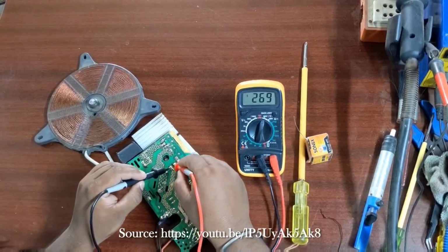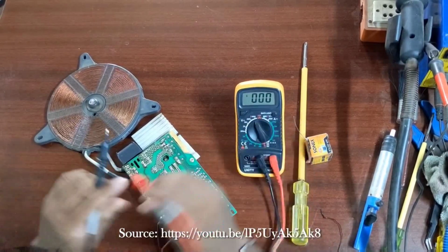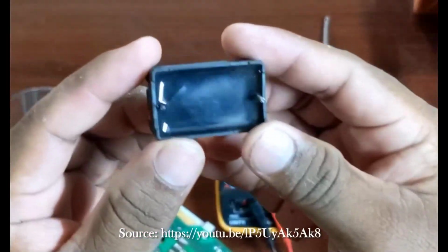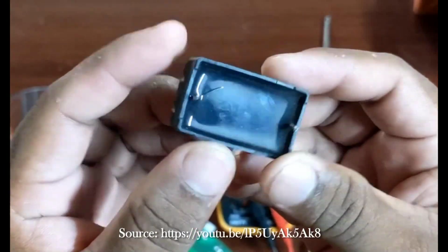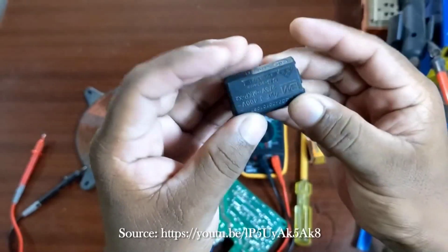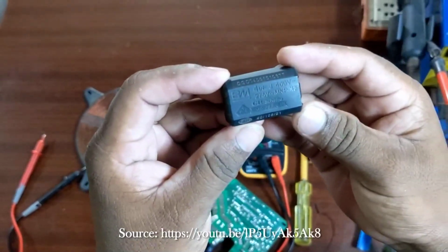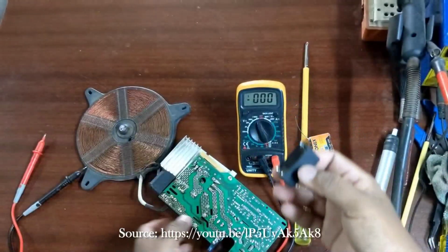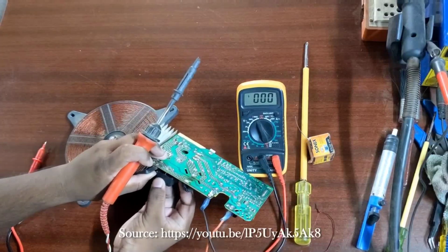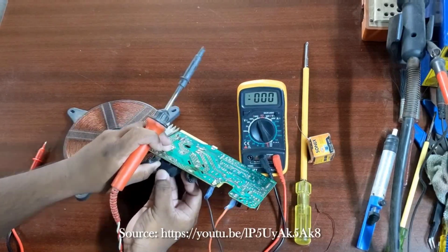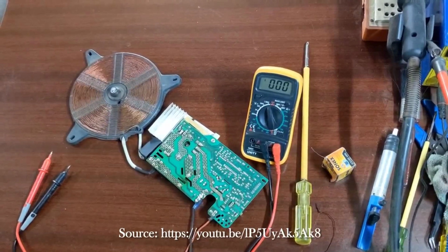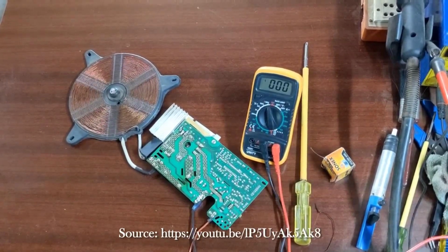As the voltage level is not showing correctly, let us check the capacitor of the circuit. As the capacitor is damaged, that we have seen here, it drops the voltage level. So the capacitor is to be replaced. Now let us see again. The E9 error code is caused due to the capacitor not functioning properly.